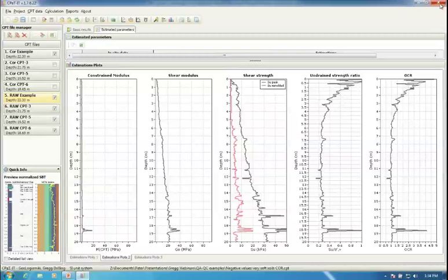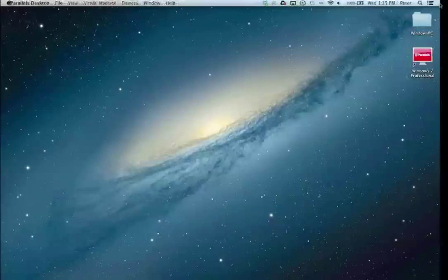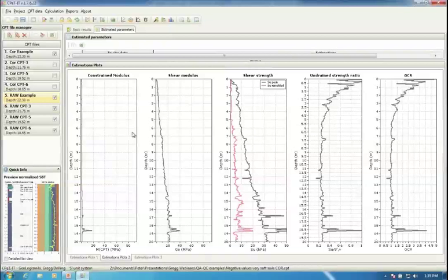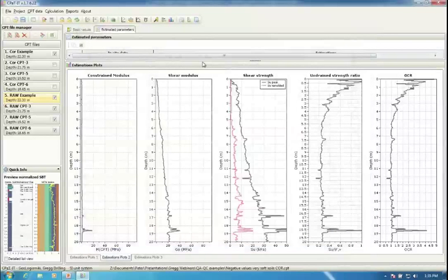Kelly and I will try to reply by email to some of the remaining questions that you asked. And join us for our next webinar. I think the next one we're going to talk about dissipation tests. I haven't yet really covered dissipation tests, about the theory behind them, how you do them, and how you interpret the data. And there is a little module in CPT that allows you to interpret dissipation tests, and so we'll show some examples on how you do that.